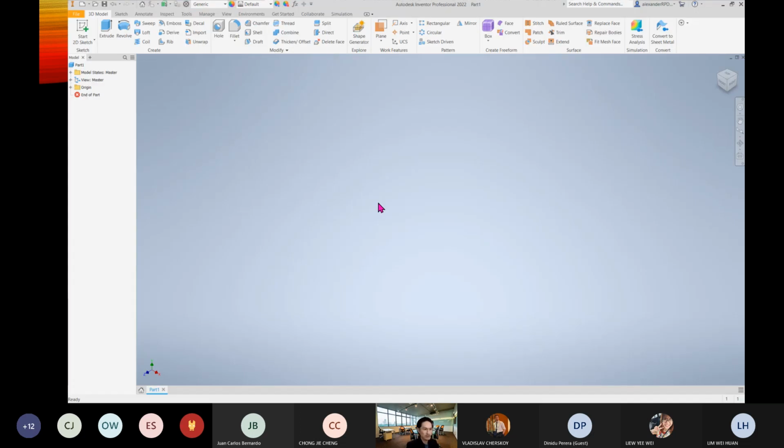Okay, zoom in, zoom out, no issue. You scroll your mouse, zoom in, zoom out. And then when you press the scroll, just the basic one, pressing the scroll, that basically is move. You can see the hand icon, just like you are pressing on a piece of paper, and then you move your piece of paper. So pressing the scroll, it is move. I know in certain CAD software, this move you need to combine with another key. Okay, so this is Inventor. Scroll in, scroll out, zoom, no issue. But now when we scroll in, scroll out, we didn't see the effect. This is for the move.